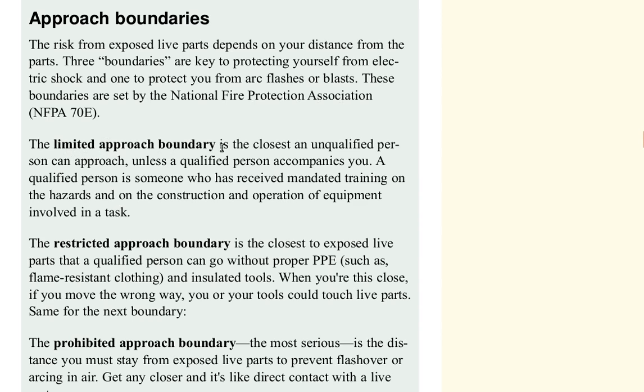The limited approach boundary is the closest an unqualified person can approach, unless a qualified person accompanies you. A qualified person is someone who has received mandated training on the hazards and on the construction and operation of equipment involved in a task.